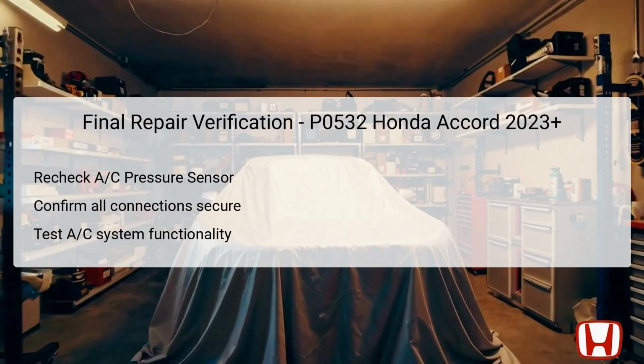After all troubleshooting steps for DTC P0532 have been performed and repairs are made, it is essential to conduct a final verification to ensure everything is functioning correctly. Start by rechecking the AC pressure sensor to ensure that it is properly installed and connected. All electrical connections should be secure, with no signs of wear or damage.